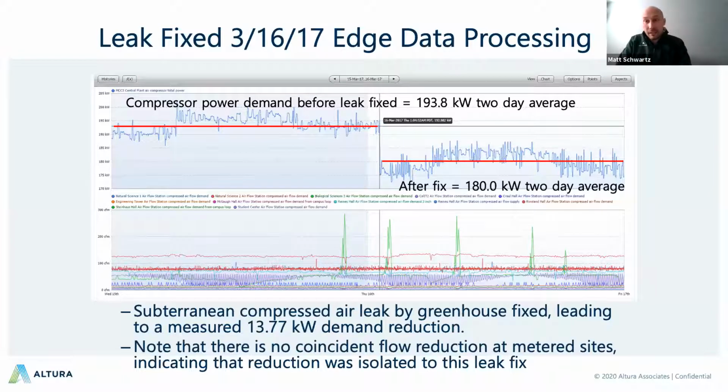So now you're looking at data coming right out of an edge controller, running analytics, and through engineering, and we're not taking people out of the equation here, engineers at Altura studied this data using analytic rules to find things like this. You're looking on 316 at a compressor leak that we identified because the compressor was operating at higher points than we expected.